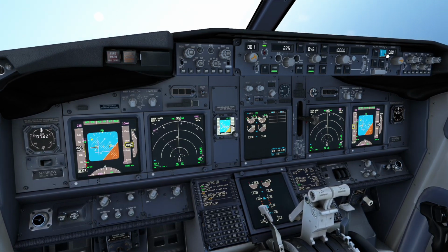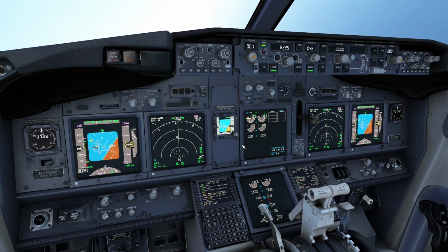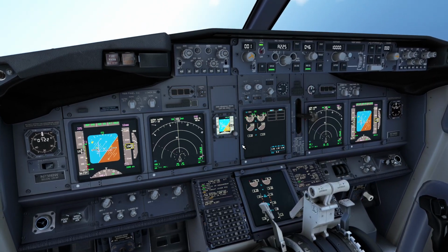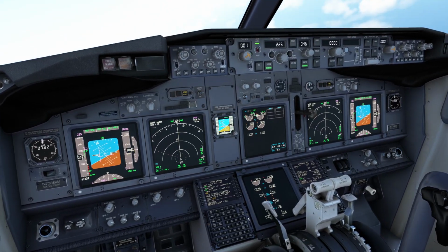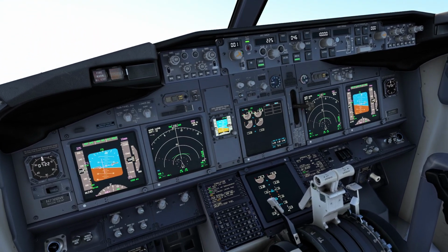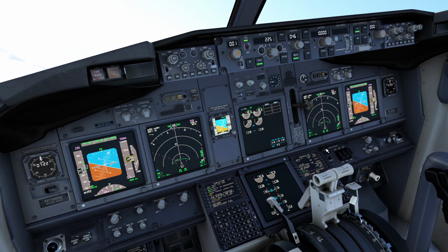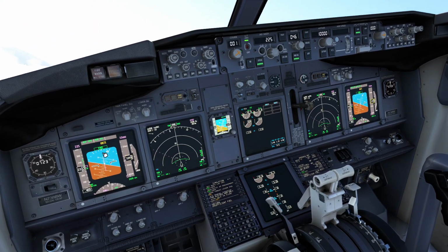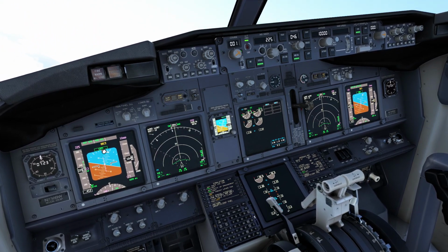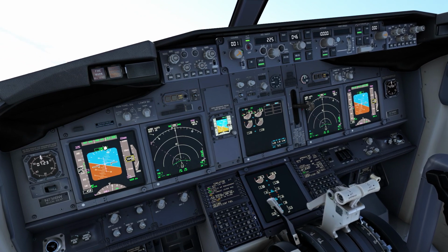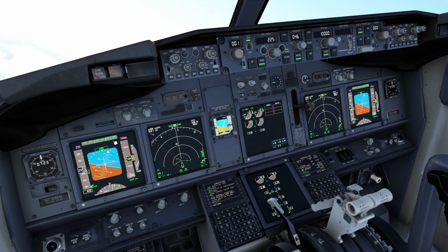As you can notice, it does not engage, okay? So now I need to go back towards my flight director, which is now to the other side, and now I can engage my autopilot. As you can notice, it just engaged in command, and you need to give it a pitch, which is altitude acquired now, which is fine, okay?